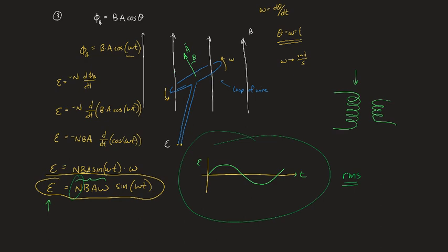It's called root mean square. What you do, to get an idea for how much useful energy there is, is square all the numbers first, which turns this into a signal that looks like that. And then you square root it. Root mean square: you take this, find the average, take the square root. And it basically works out to be about 0.707 of peak.